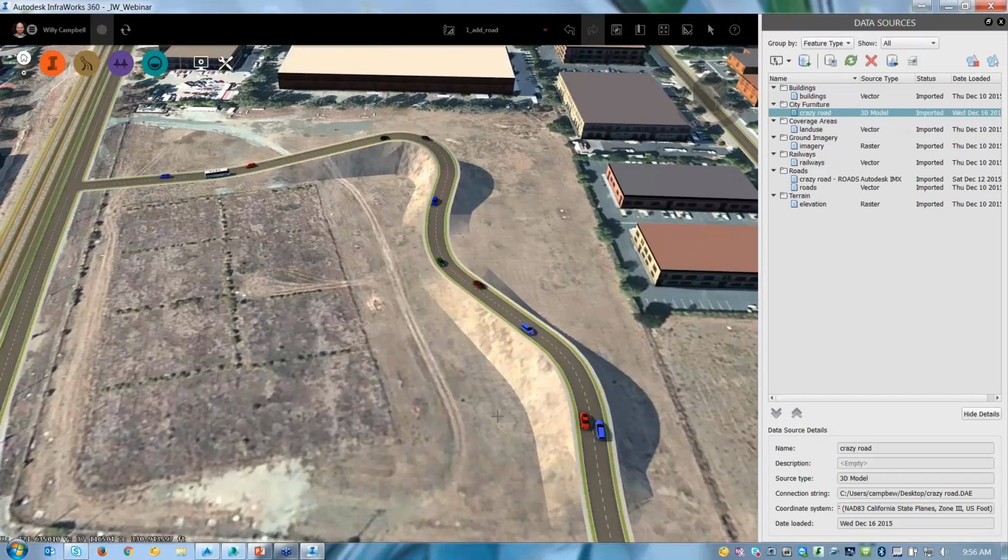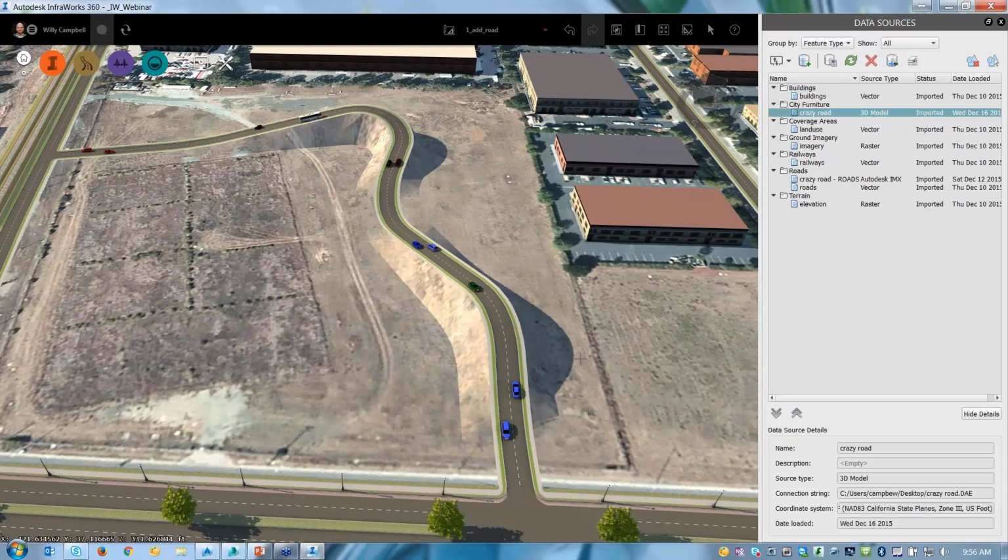Now, the 13 and the 3 and the XY difference are going to be specific to this project, but when I discovered and figured out how to make this change, it literally took me about 2 minutes to make the change. So it's not a big deal, but it is something that you're going to have to be aware of. This is affected by the further away from the equator you are, the more the skew is going to apply, and the longer your road or the bigger your project. So if you have a massive project, you're going to get a bigger skew. So you're going to need to look at those numbers and play with those numbers. But again, it took me 2 minutes, by a factor of 5, by a factor of 10, and I was able to get it pinned down. Everything lines up where it's supposed to, and that's it.